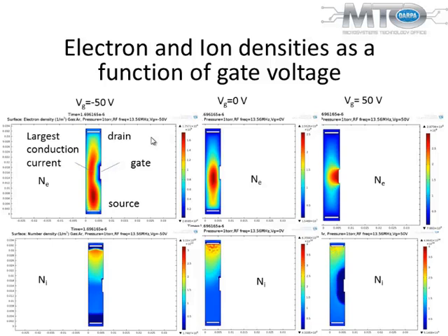This is for the electron concentration. Both of these operations are possible. Now, in order to speed these things up, electron mobilities are much, much higher than the ion mobilities, at least by 2,000 times. So by going into this regime of operation, you can make them much faster than by trying to control their conduction through the ionic concentration. This is something we have learned during the past 6 months. To speed these things up, we really need to take advantage of these different types of controls that you can have inside the device.